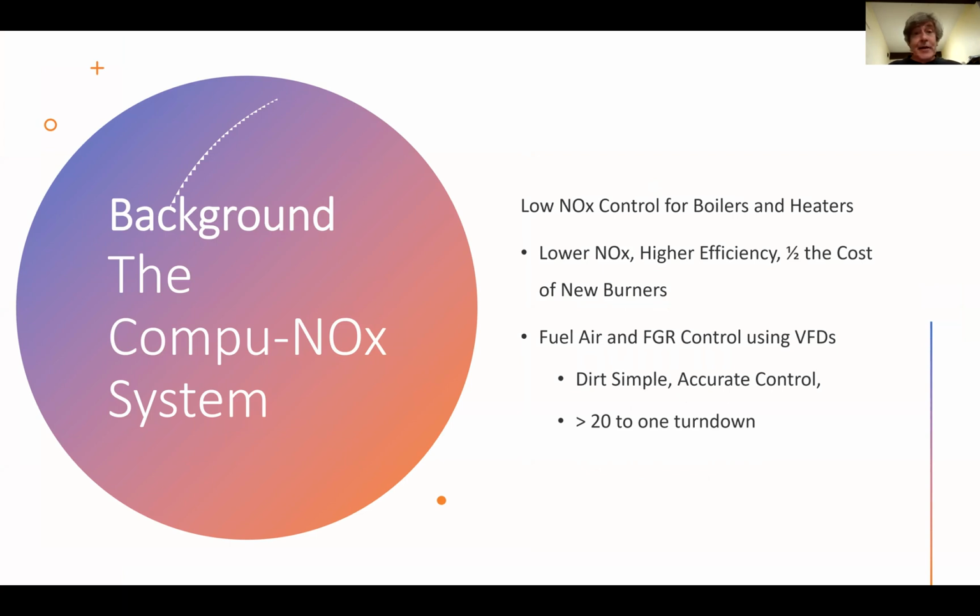It started back in 1985 when I was doing a research project for Southern California Edison, modifying a boiler with a non-selective catalytic reduction system, which is a car catalyst. We were putting catalyst in the back end of a boiler breech and then running the boiler stoichiometric. To do that, we had to use variable frequency drives to control the combustion air fan, essentially matching the parabolic system of a fan with the parabolic system of a boiler and running the fan speed as a function of fuel flow.